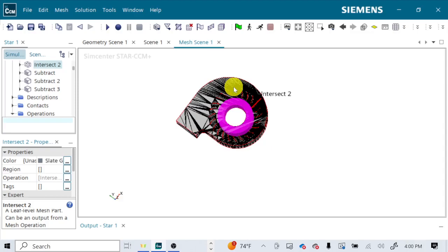But you always need multiple regions of air. In this case, we're building 3. One before, one rotating, one after. But the same principle holds regardless of what you're doing with rotating blades, and also regardless of how you're doing it. There's multiple ways of simulating this. All of them need this to be a separate region.